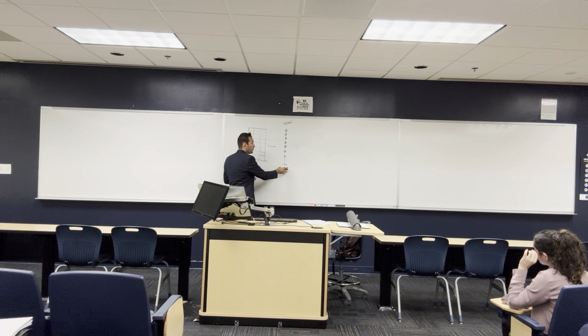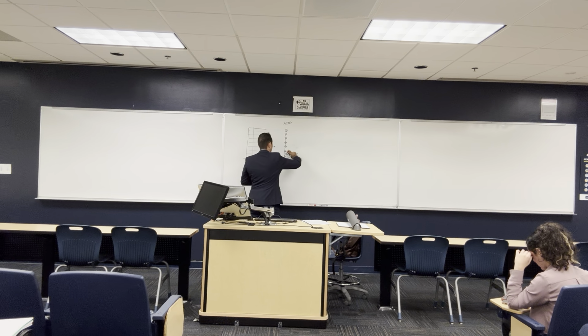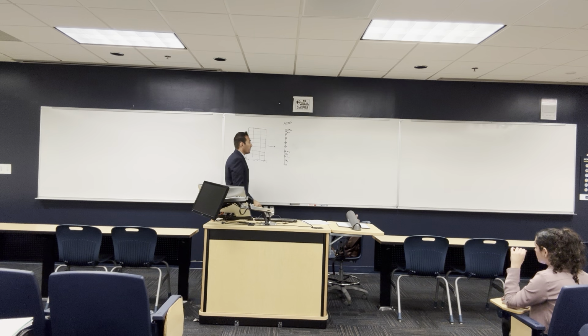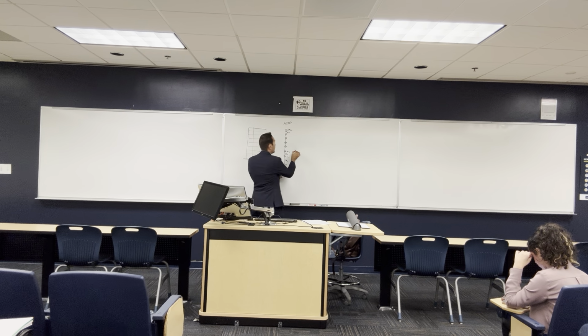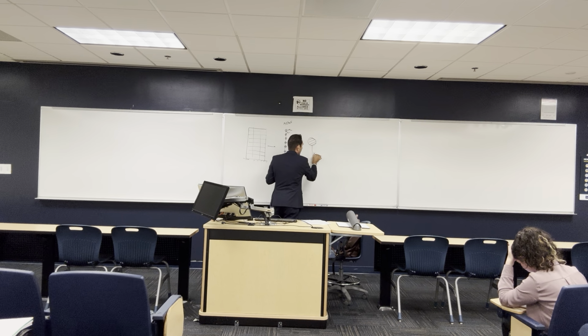And then this multi-degree of freedom building has some stiffnesses that are based on the stiffness of the building, like K1, M1, K2, M2, up to Kn, Mn, until the final story. The thing is, this system is still complicated. So we try to convert all these masses to 1 mass and 1 stiffness. Something like this, and this is 1 mass.